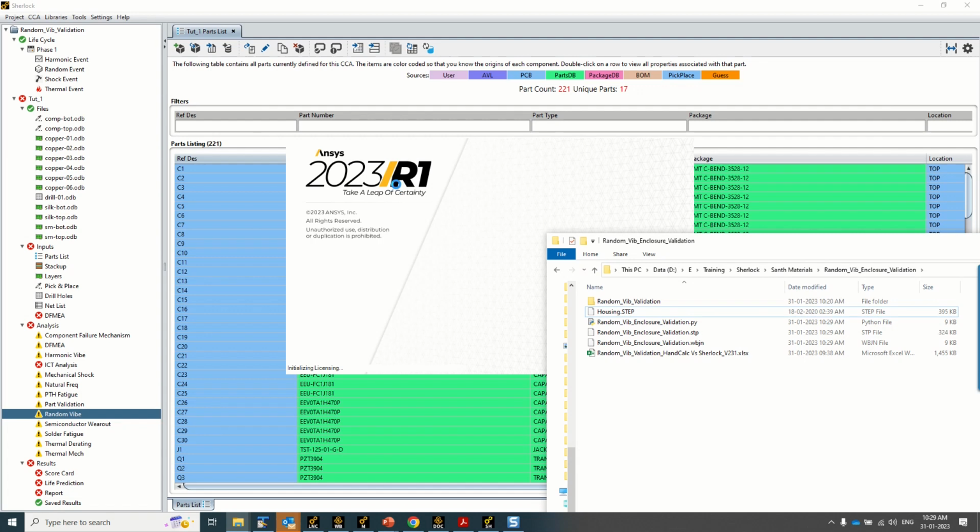That's what is happening here, and set up necessary systems to import this STEP file, and also will assign the necessary material properties for the PCB and all the components, etc. It's going to take some time to open Workbench, import the model, assign the material properties and open Mechanical. You need to wait for a few minutes.